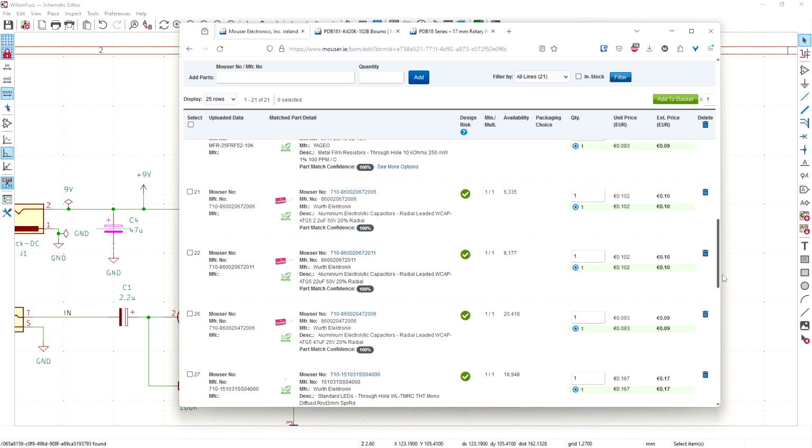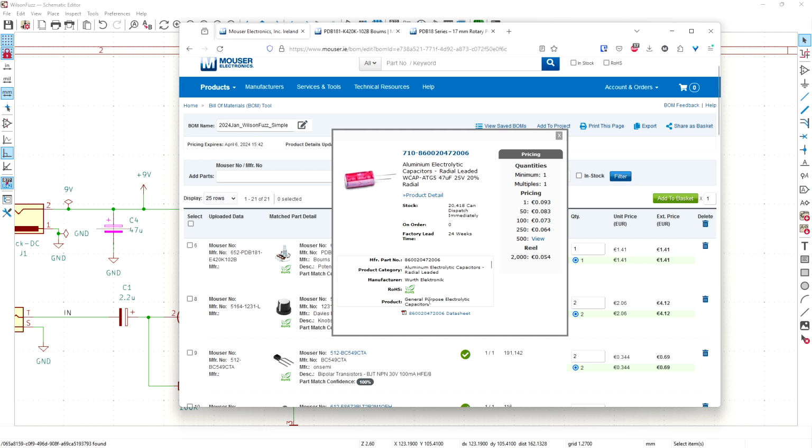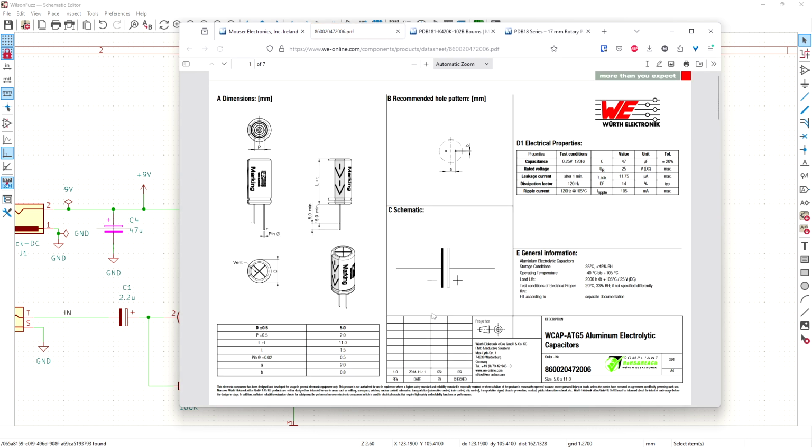I'm getting into too many things now, but it's the same voltage rating. As long as it's over 9 volts, it should be okay. But keeping in mind that they lose performance if you're closer to the intended voltage, so it's better to have this a bit higher. 25 volts is great. I think it's going to be fine.